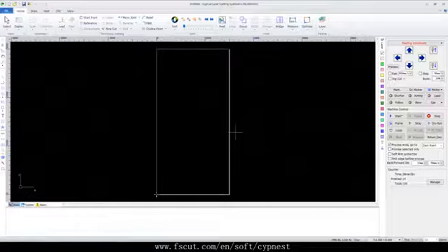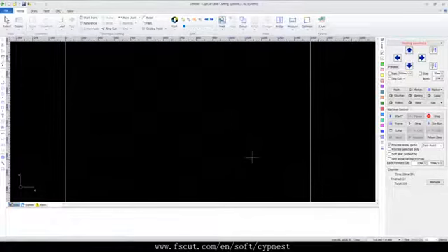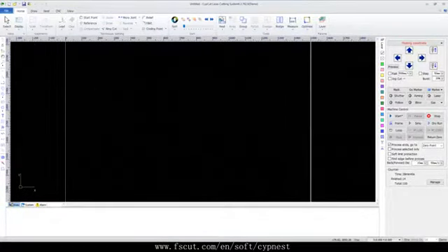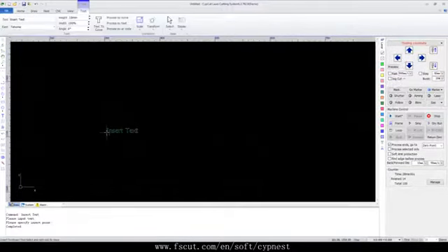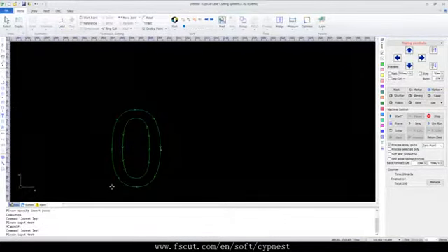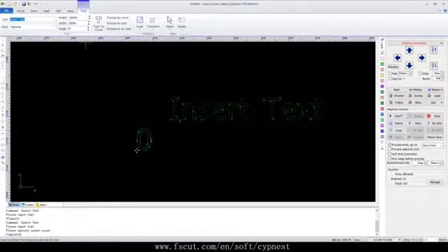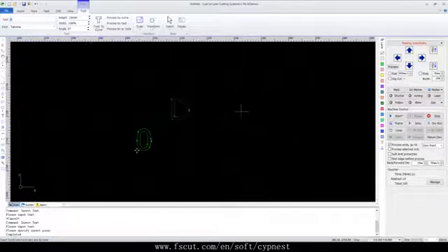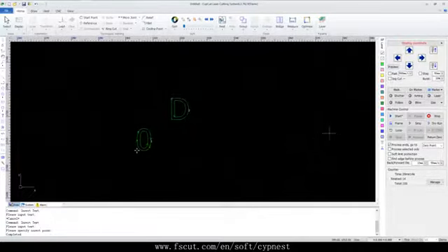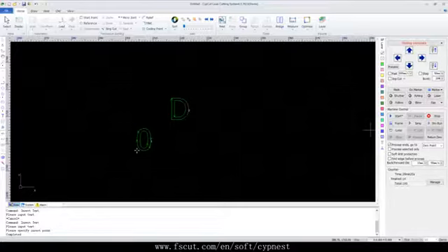When we cut a part formed with several pieces and with closed loop, typically the numbers and the letters, we may need to bridge it. For instance, if we got the number 0, and the letter D, if we don't get it bridged, both of the round and the ring would fall down, and only leaves a single hole on the metal sheet, which wouldn't be satisfying.